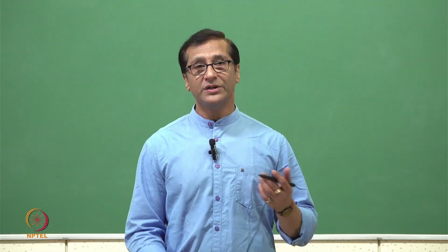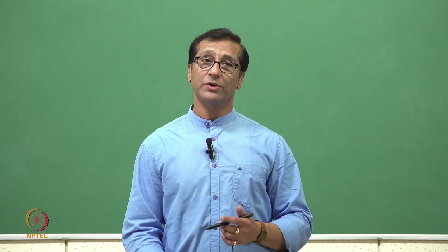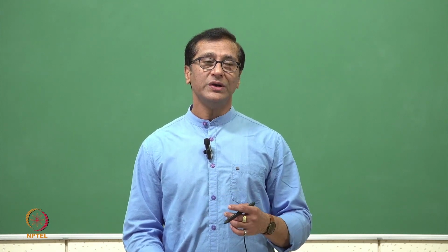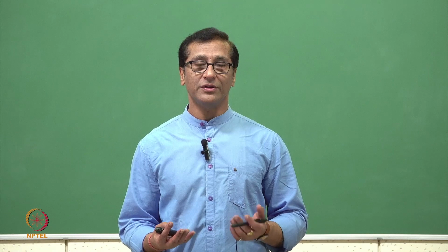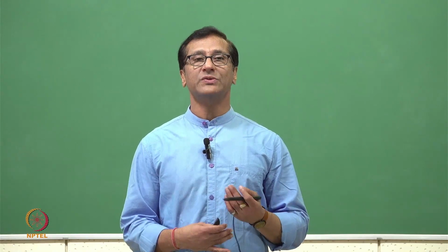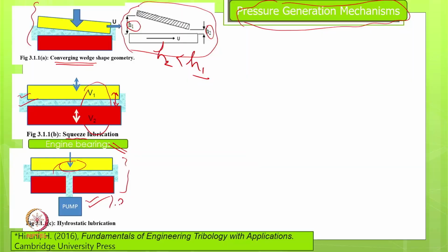Now, why are we talking about hydrostatic? Because in one of the previous slides we mentioned the hydrostatic bearing. The second thing is, how will we bring the lubricant into a hydrodynamic lubrication mechanism? There should be some way, from some place it should come. That's why many times we use a pumping mechanism. Of course, for hydrodynamic lubrication, it can be 1.2 bar or slightly above atmospheric pressure. When we come to the hydrostatic bearing, it can be even 10 bar to 100 bar. There's a possibility. So this is the difference, but again we are bringing some pressure from outside.